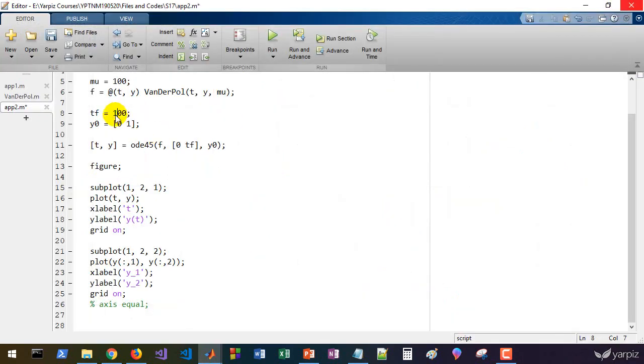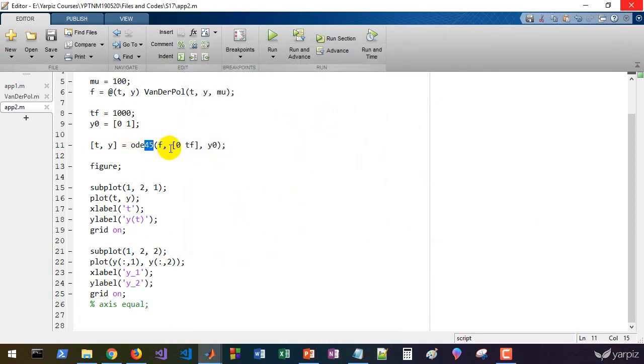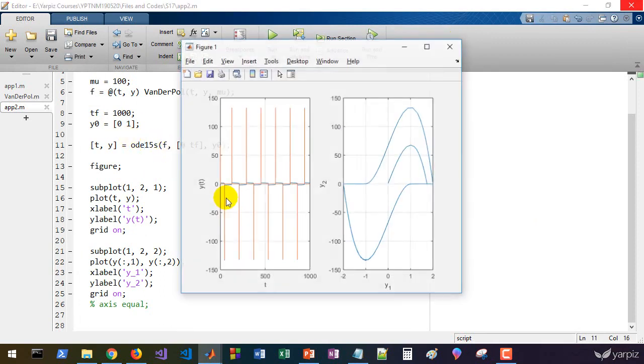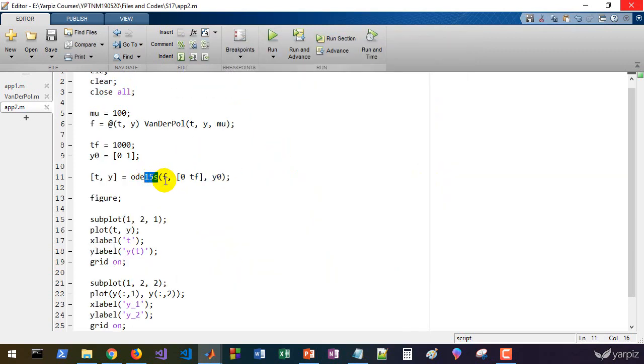However, if we increase this, the program will be slow at evaluating this stiff model. And we can try, for example, 1.5s instead of this to have a faster response and a better computational experience. And this is one case we use stiff solvers to deal with stiff problems and have much more speed of computation. Okay, let's return back to 4.5s, and that's it.